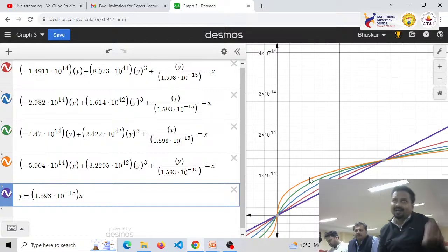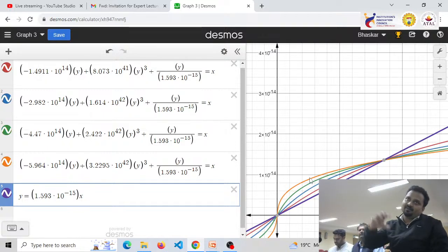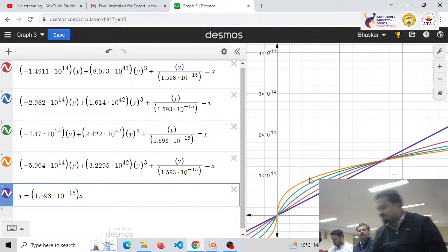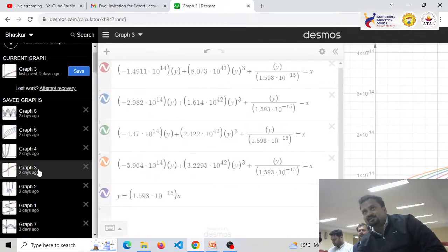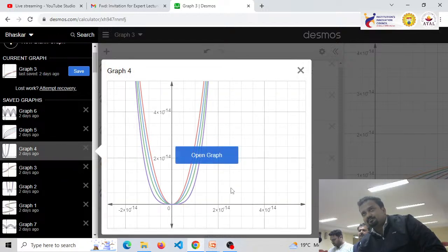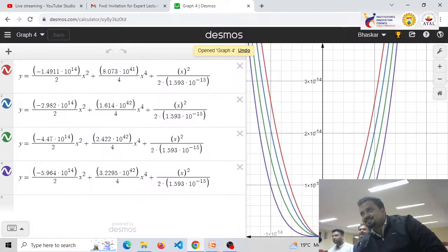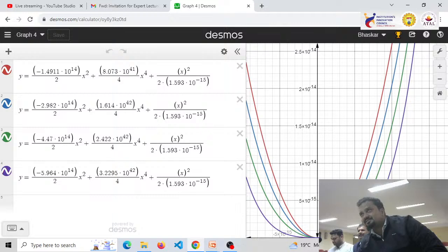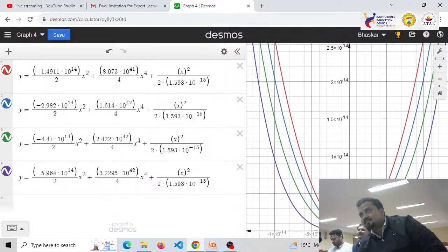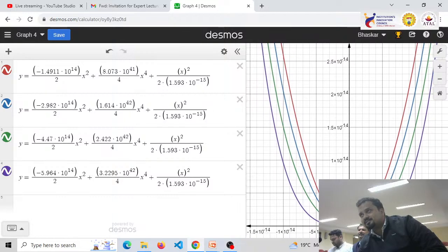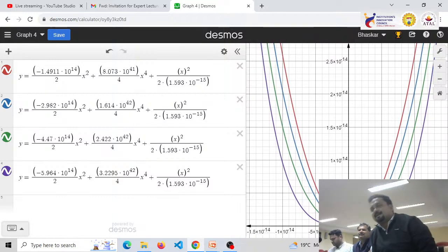Now I'll move on to U versus Q. Like we have discussed the energy versus charge for the isolated ferroelectric capacitor, and now we'll move on to U versus Q of the heterostructure. Now this is the perfect graph. These are the graphs for the FE-D heterostructure.